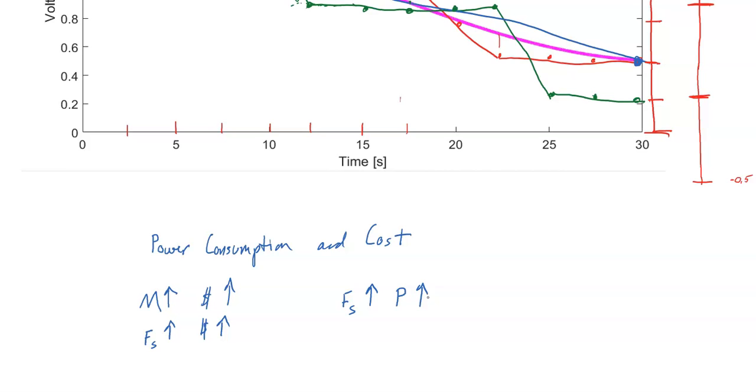And so if we're doing that 1,000 times a second, or 100,000 times a second, or 1,000,000 times a second, we're suddenly now utilizing that small amount of power it costs to take the measurement at an incredibly high rate. And so our total power consumption can go way up because of that.